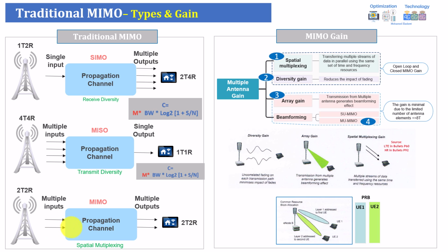For example, data 1 here and data 2 here, to the antenna to the receiver, but the receiver must be supported as well to be able to receive from two different directions. It's usually happening in a very good radio condition, and this can double your throughput. For example, instead of getting one data stream, you get two, so it can double your throughput.